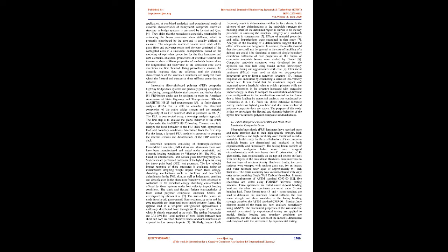Development of core materials has continued throughout the past 65 years in an effort to reduce the weight of the sandwich laminate. The cores used in sandwich construction can be divided into four main groups: corrugated, honeycomb, balsa wood, and foams. Balsa wood was the first core material to be used in sandwich construction. The use of sandwich structures is growing very rapidly around the world. The need for lightweight structural elements with high stiffness for bridge applications and trucking industry increase the demand for sandwich construction technology made of composite materials.